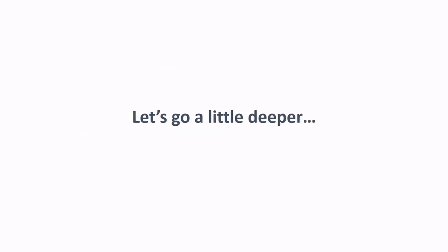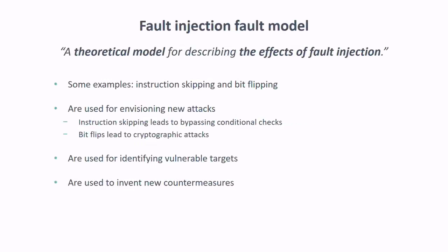But there is something more here, and we think it could be really interesting also for this kind of attack. But let's go one step back. Usually, you don't know what happens, so in order to research fault injection, you build a model. It's called the fault model. For example, we assume that this fault might allow you to skip an instruction, such as when you have an if or a check, and you actually skip the instruction, not executing it.